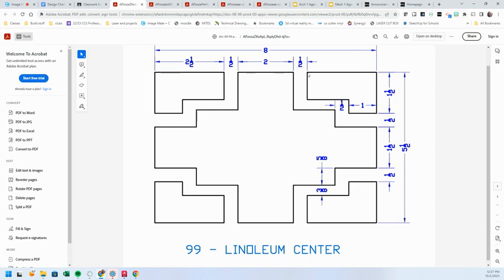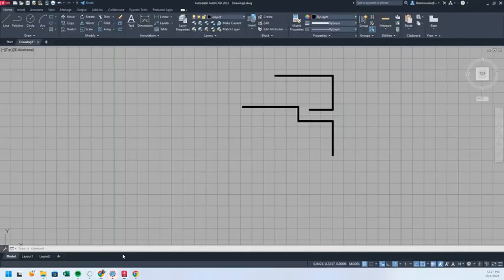And then we also have, let's see here. We're going to go for this one. I want to go up 3/8 of an inch. So I'm just going to use my offset command. I go to offset and then I type in 3/8 before I click anything and hit enter. Select my line and move it up. Notice I kind of exaggerate how far up it goes.